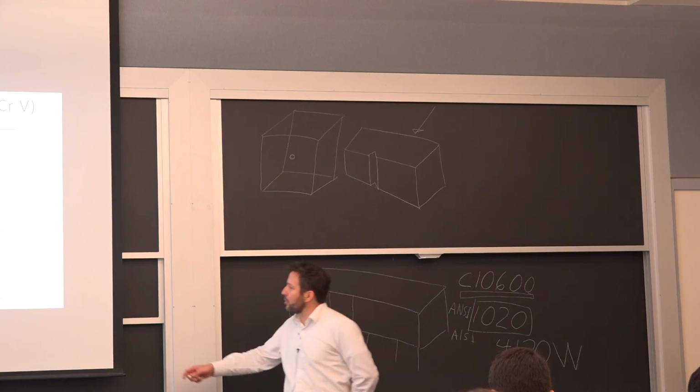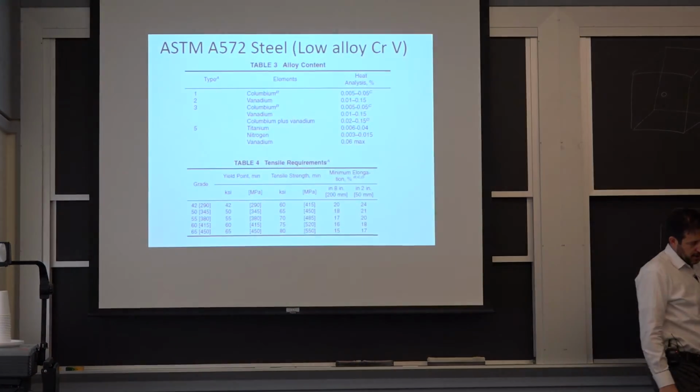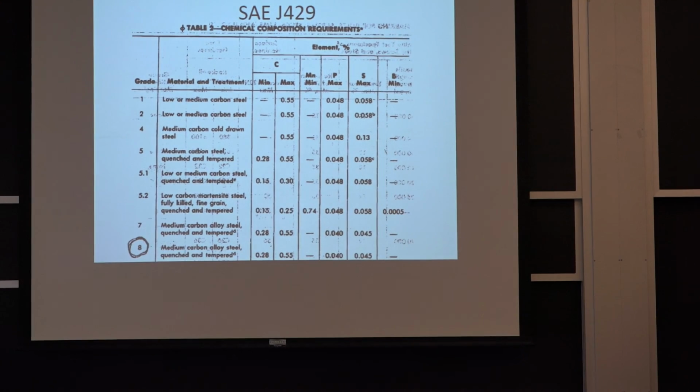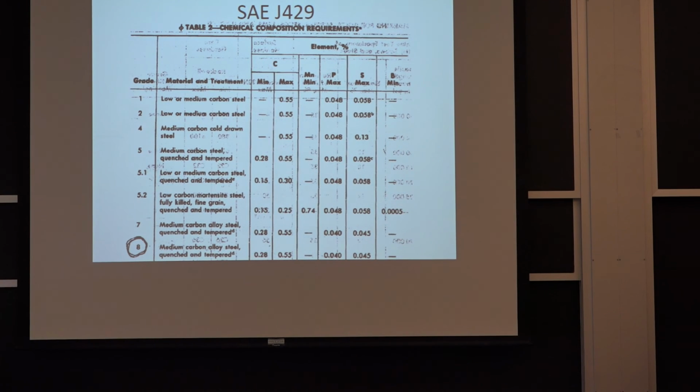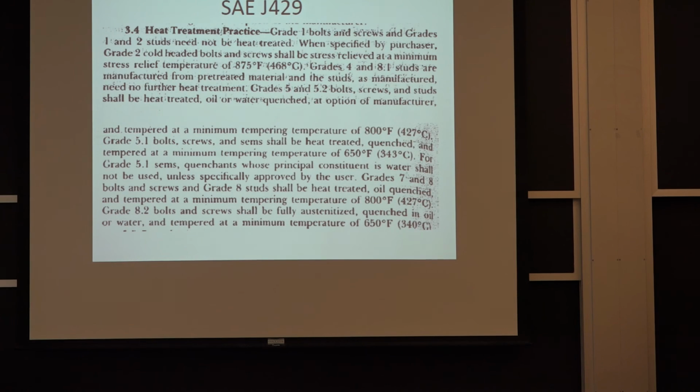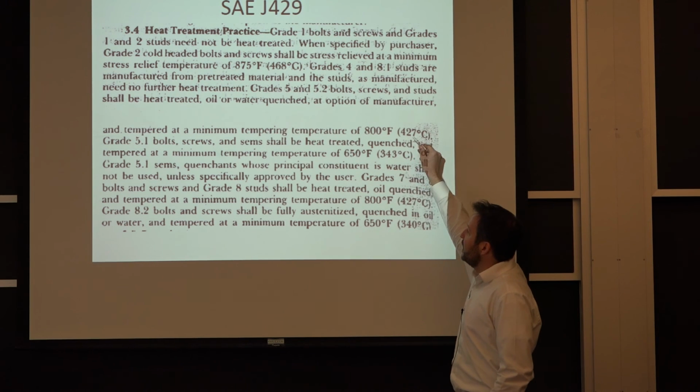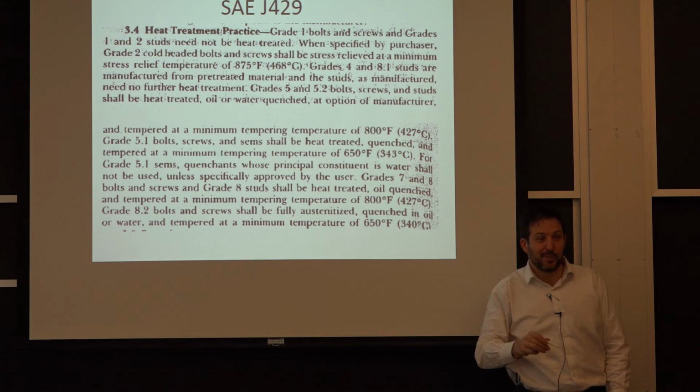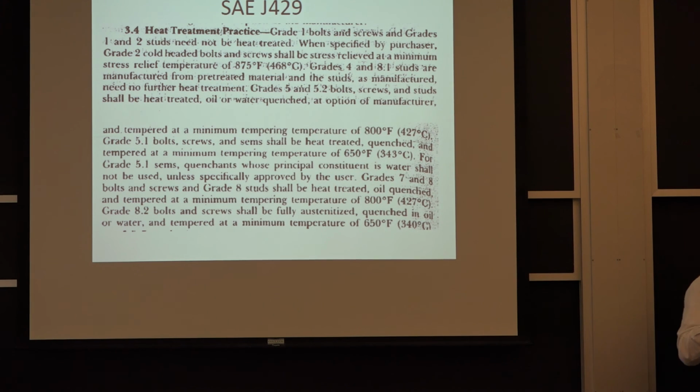So there's a mechanical property requirement here in that ASTM. And if you're looking at high-strength bolts, a grade 8 bolt by SAE will have composition here. It has mechanical property requirements, and it also has heat treatment requirements. They're very, very specific. The reason I copied this one is that it's very rare that a standard will tell you how to temper your steel very precisely. But when it's becoming a relatively high-strength material, you can't take a chance. You don't want something to be brittle if it's supposed to be a good high-strength bolt. So you go all the way to that step to figure it out.